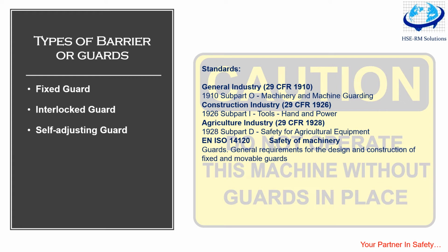They are most often used as enclosed points of operation or other hazards where the operator doesn't need to interact, like fan blades and flywheels. A guard that completely encloses and prevents access to the dangerous part is called an enclosure guard. Enclosure guards are typically seen in power transmission components like sprockets, chain, flywheels, pulleys, gears, shafts, and wheels.